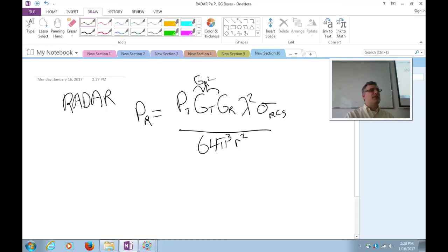And you see there's some of the same issues at work here. Generally speaking, there's a lambda squared in the numerator, which means there's 1 over frequency squared dependence in the denominator. You're going to get a lossier system. However, you can make up for that and even turn the high frequency from a liability to a benefit by moving to a directional antenna that points.